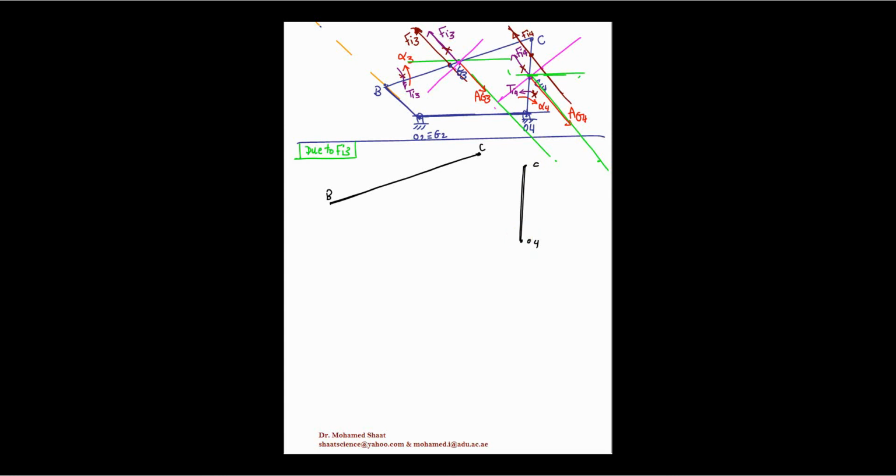All right. Then what? Your objective is just to identify any forces acting on this link, assuming that Fi3 has a value, but Fi4 is already 0. Fi4 is already 0, so there are no forces acting over this link except the other forces. There should be one force here and another force there, right? And how about this link? There should be a force, which is Fi3, already acting in the middle at this point. So that's why it was important to identify this point, which is the point of intersection of this Fi3 with link number 3.